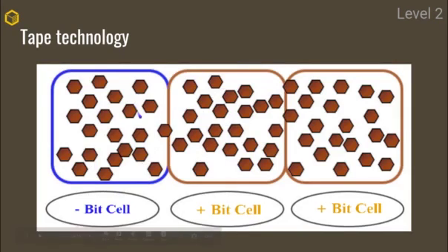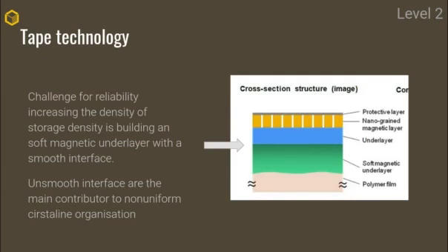Now you can see here that my crystals aren't very, very well organized on my tape, and so I have to widen the area that I am considering for one memory cell in order to have the reliability I want. Now, if I could make my crystals better organized, closer, then I could reduce the area I need per memory cell and so increase the capacity of my tape.